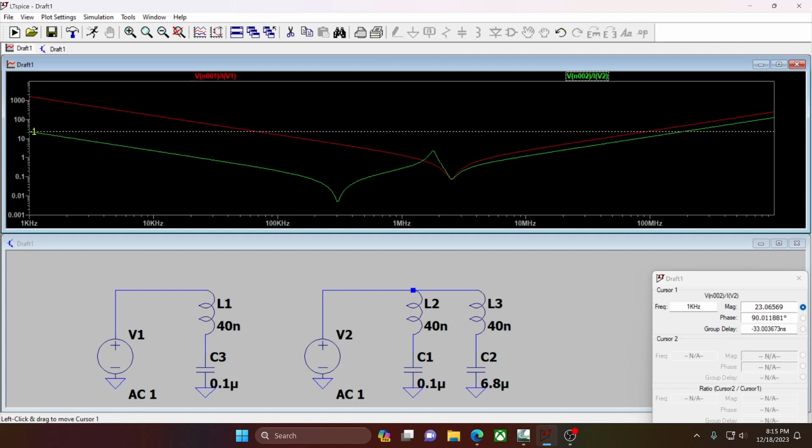Here, let's get this. How far do we actually get? We're getting to our 25. All right, 200 megahertz. So we're definitely going to have to decrease this inductance. Or alternatively, as you saw, put more 0.1s in parallel in order to make that happen.